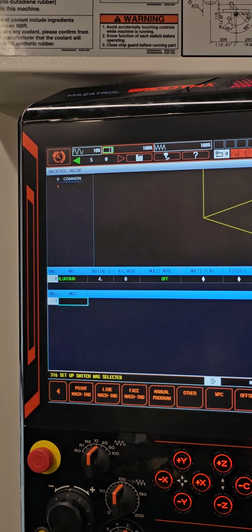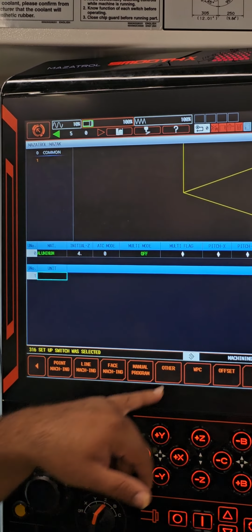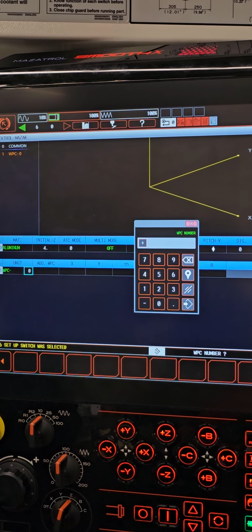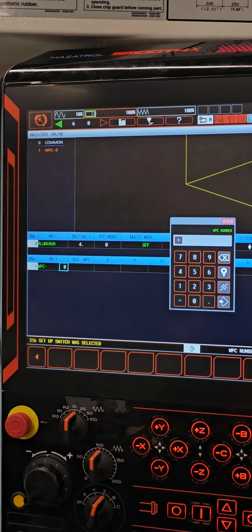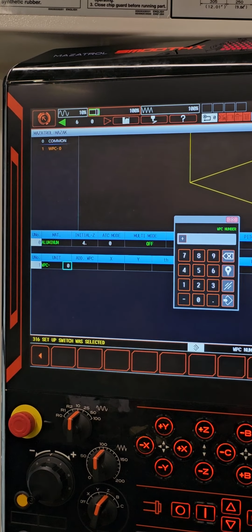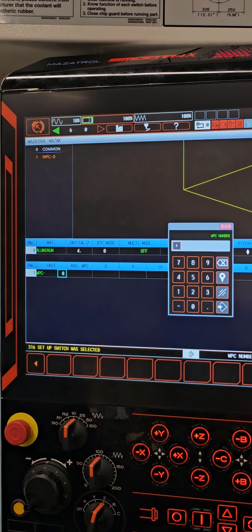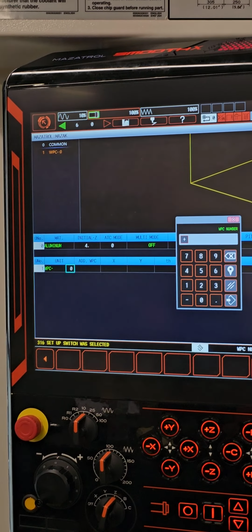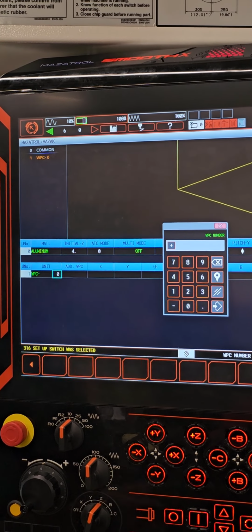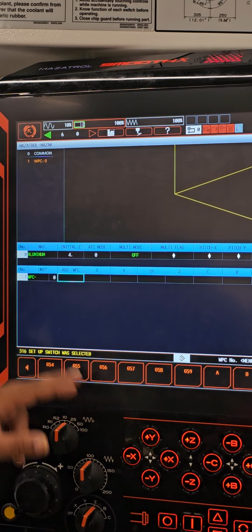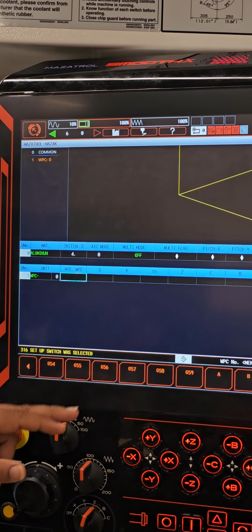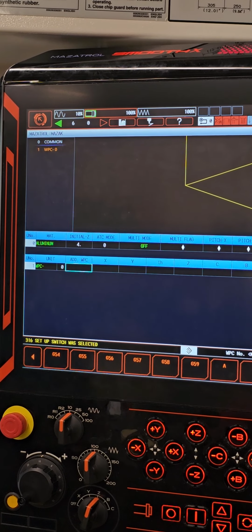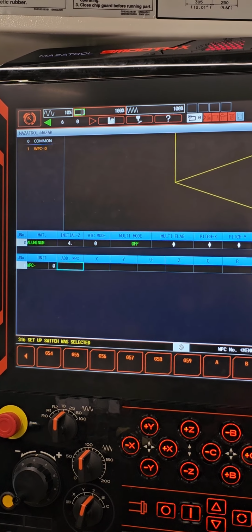All right. So unit number 1, we're gonna hit WPC. Workpiece coordinate. WPC is pretty much like our G54, WCS on the Haas, all right? Where your X0, Y0, Z0 is gonna be, correct? Then right here it says unit number. Which one? We could set multiple WPCs, right? But for ours, we're just gonna hit 0. So here it even tells you, do you wanna add one? No. You wanna add a G54, a G55, a G56 on there, right? So we're just gonna skip over that one because we're not gonna add any, right?